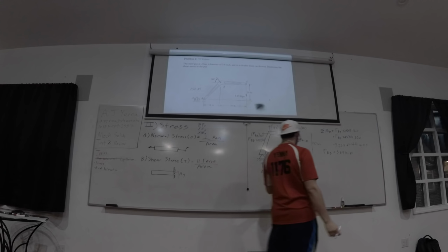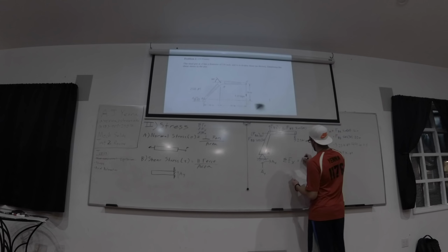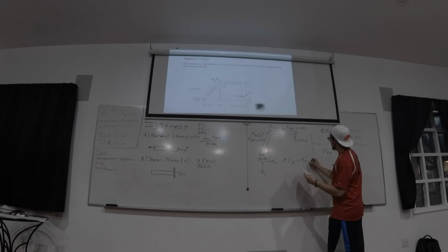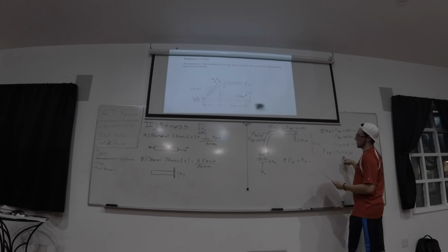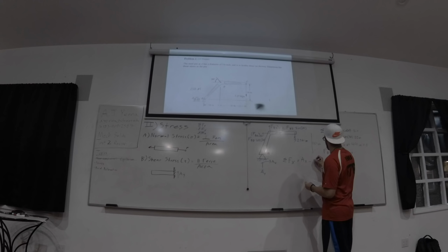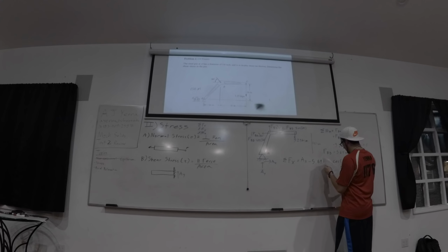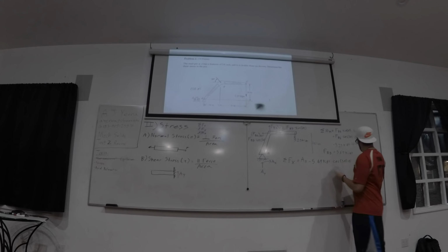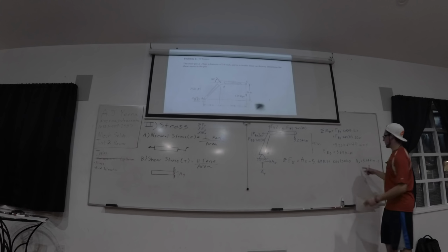So now we're solving for Ax and Ay, same thing. The other two equations are summation of force in the x, which is positive Ax because I assumed it to the right, minus FBDX, which is 5.69 times cosine 50. And Ax becomes 3.66 kips to the right.